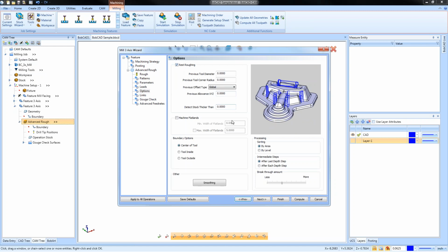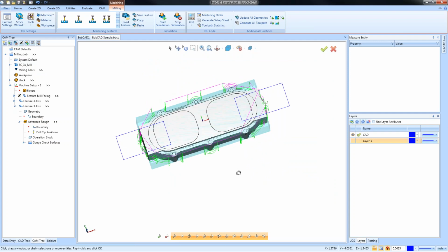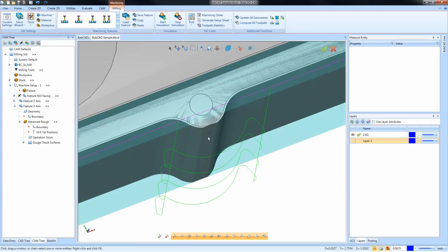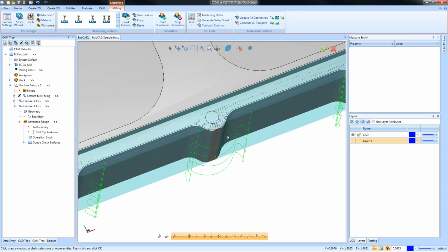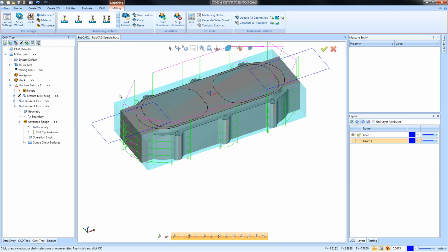This would allow us to get rid of some of the whisker cuts, right? Is what I'm looking at there. But we're not using rest roughing here. We do see some steps over here, and I believe that may just have to do with the stock that I was leaving and the size tool that I'm using. But you could see how it was able to target these areas here. There are other approaches to that as well, but that was just real quick.